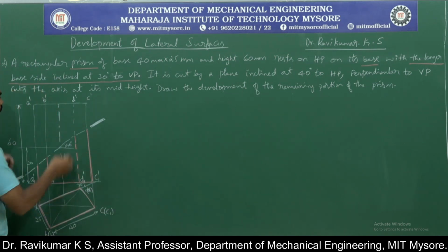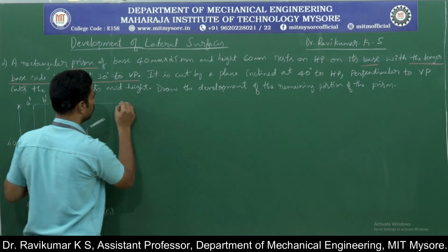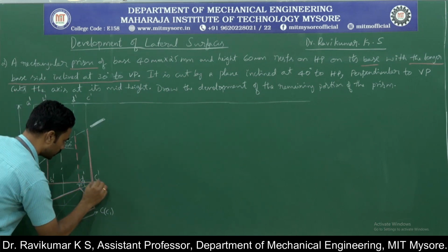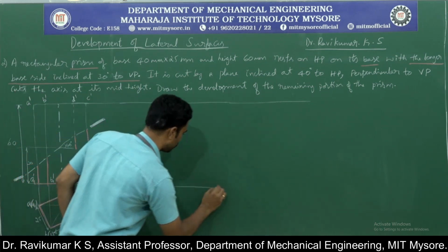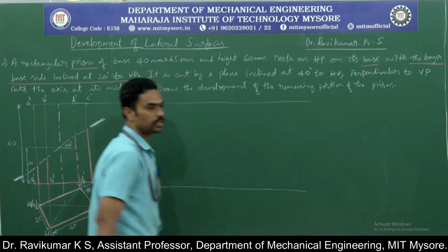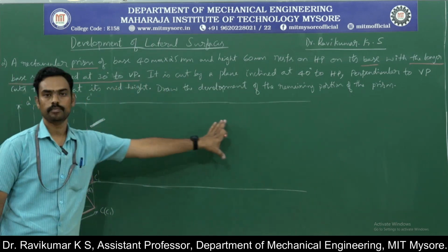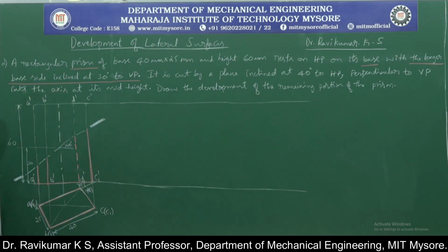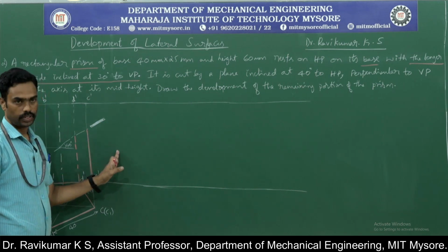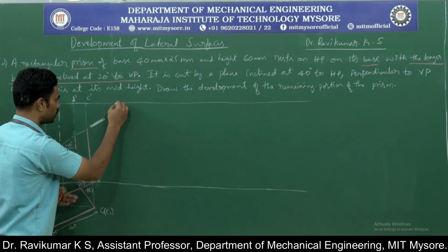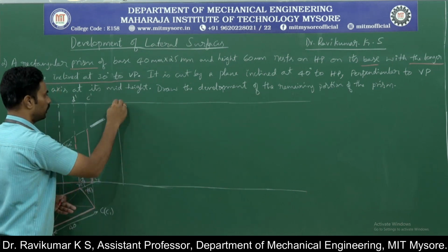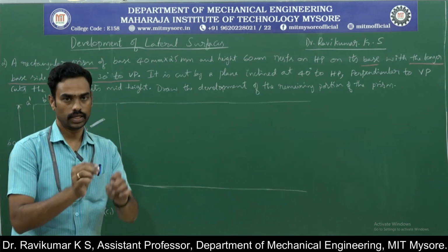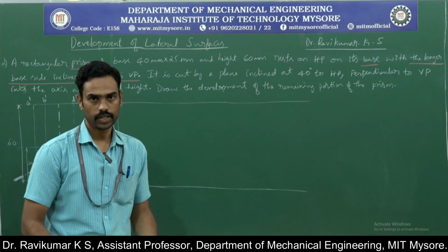Okay. So, this is the front view. I am going to use the extended line of this. So, this is the extended line. I am going to extend this. Similarly, I am going to use the extended line, something like this. Again, these two are parallel lines. It is the parallel line method. Now, you can keep a convenient distance between the front view and the development, and you just draw a line. Initially, draw lines with less pressure, that is a thin line, because only the development part should be darker.